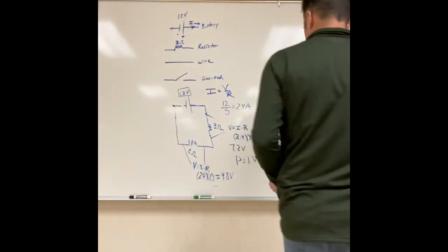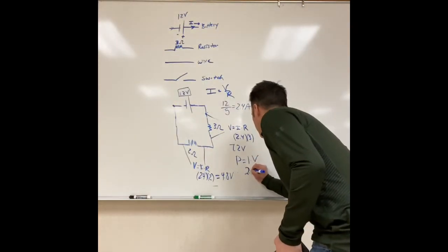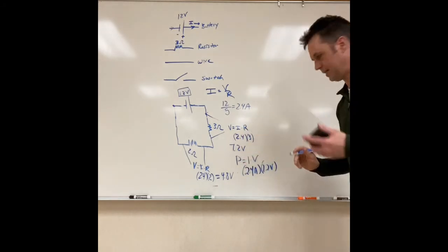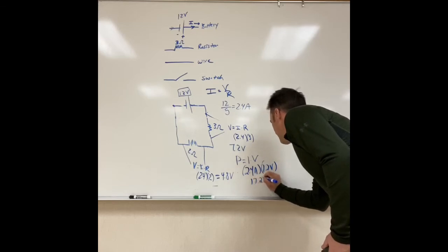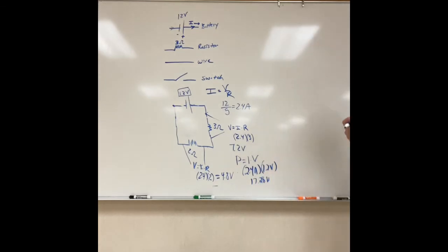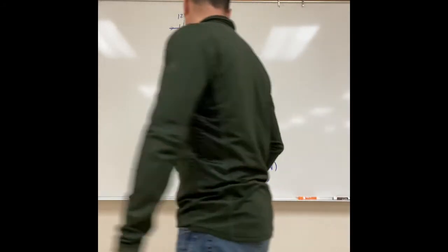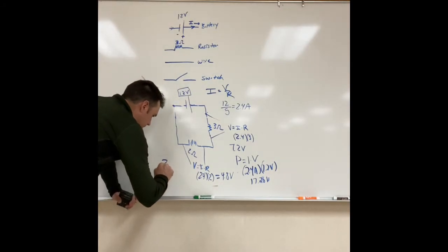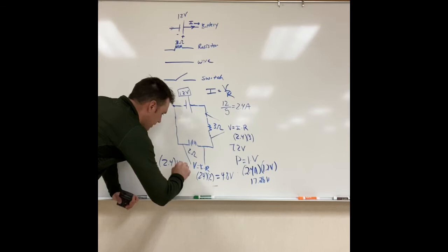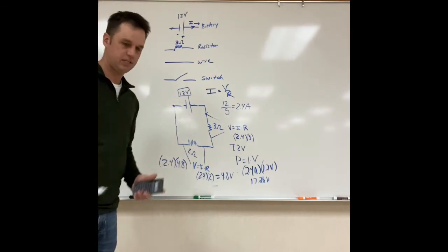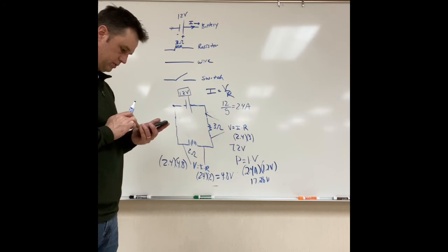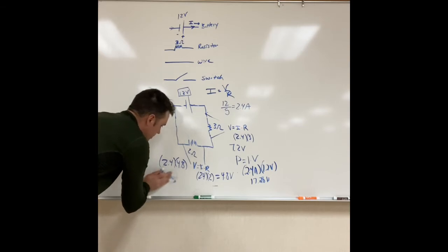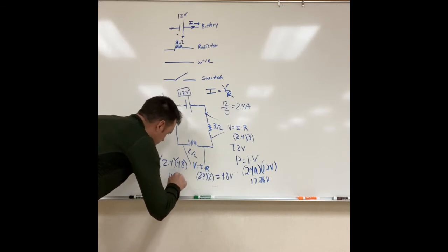All right, I have my calculator here now. So I was taking 2.4 amps times 7.2 volts, and that is 17.28 watts, or 17.28 joules per second, all right? And for this one, I have the same 2.4 amps, but I'm multiplying that by 4.8 volts, a little bit less voltage. And I get 11.52 watts.